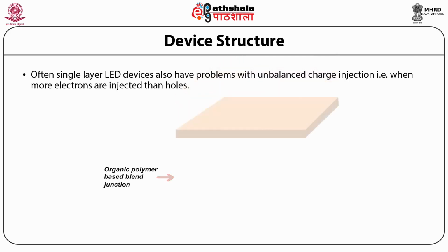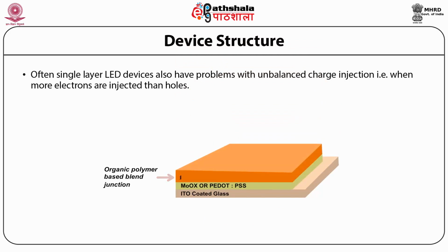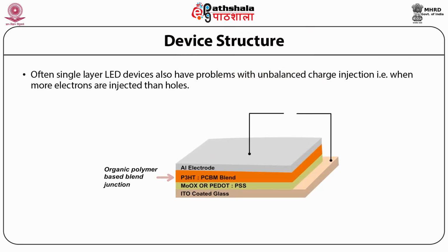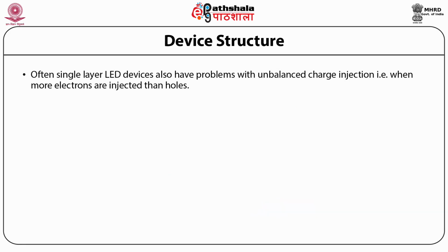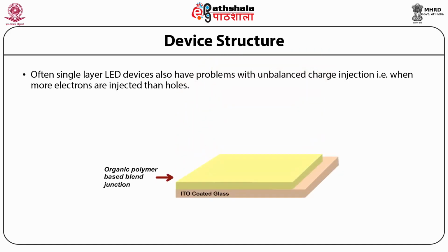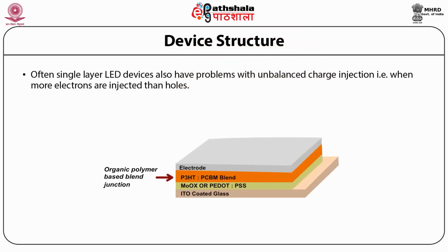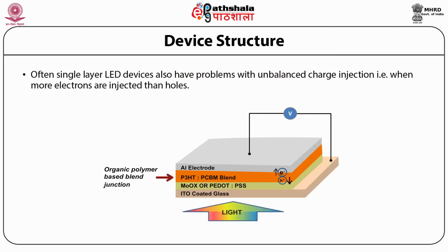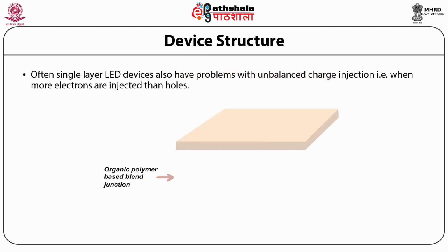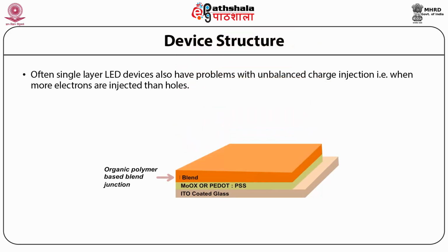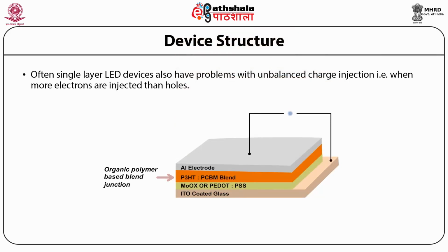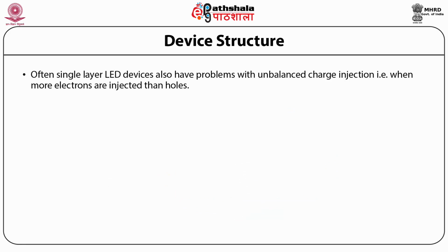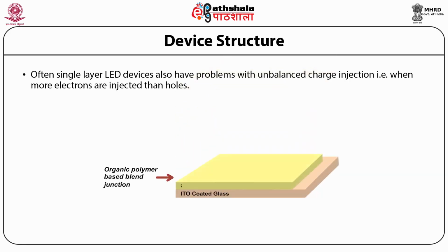As a result, the binding energy of these excitons is quite high, often exceeding 100 meV, and hence thermal energy at room temperature is insufficient to break these. Once the excitons are formed, they diffuse in the material driven by a concentration gradient, not by the electric field as they are electrically neutral, until they recombine or they dissociate to form free charges.